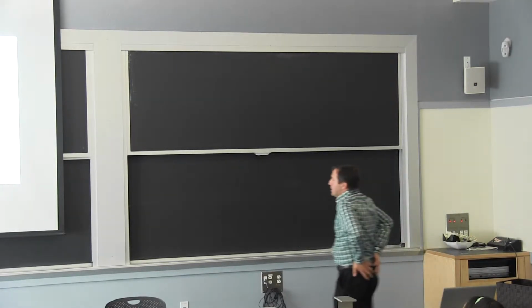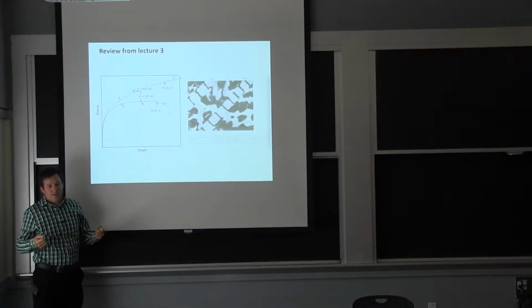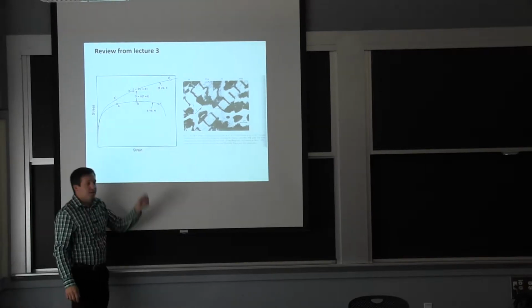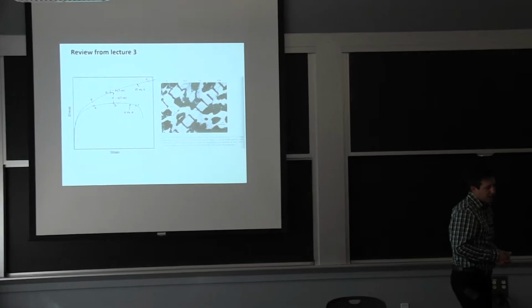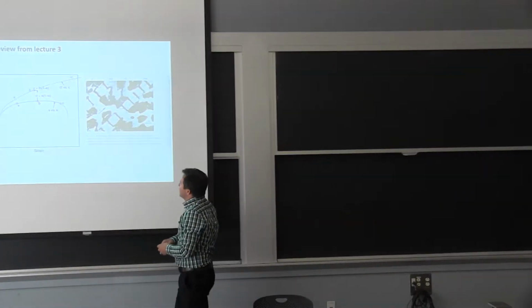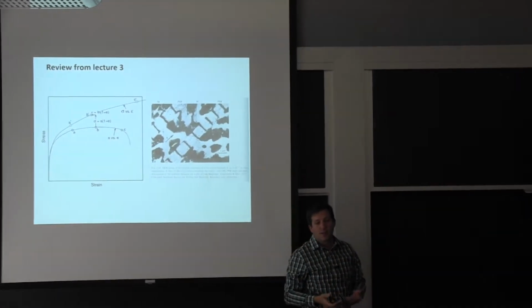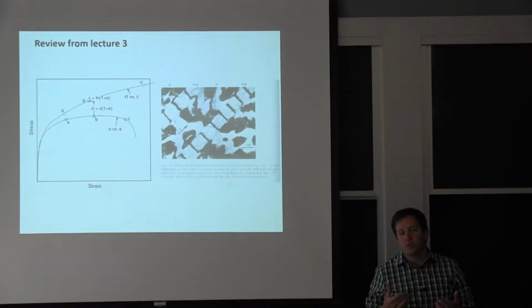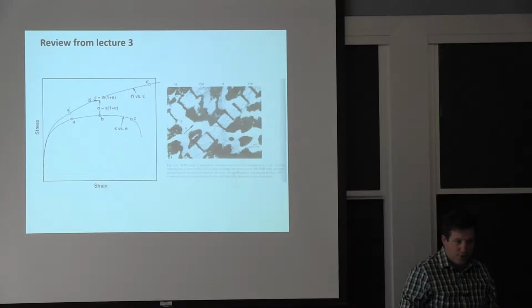The main thing, if you can remember a few things. The first one is that when you plastically deform metals, they do not soften. So what you see in a stress strain curve is associated with the necking. I think that's something that you should take out of this class. And also, one of the reasons why all this is taking place is you have this multiplication of dislocations that we were talking about, and then you reach a certain point where there is so much that it's okay, now it doesn't change anymore.